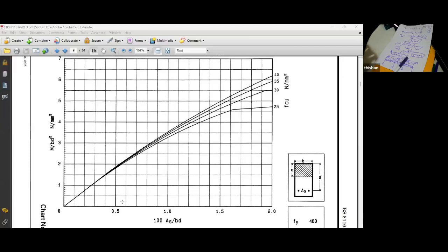Use less steel. Because when you use less steel, your structures are extremely ductile. They are very much under reinforced. They will give a lot of warning before failure. So they are good. Any structure packed with steel is not good. They are very expensive. So select large enough sections.